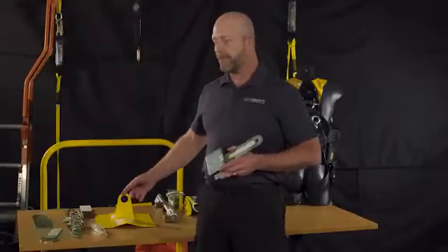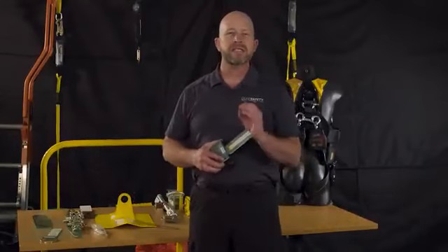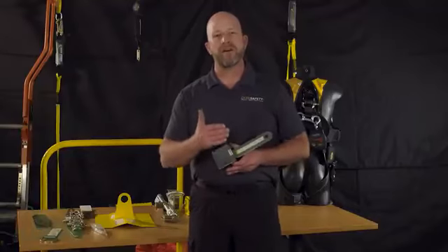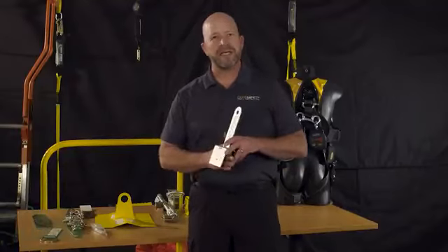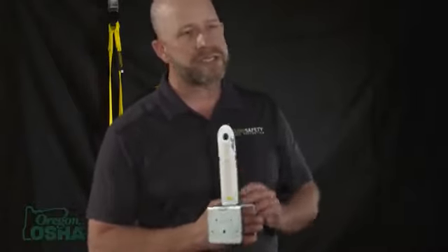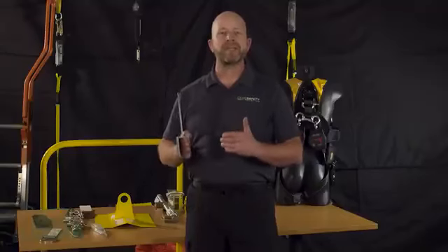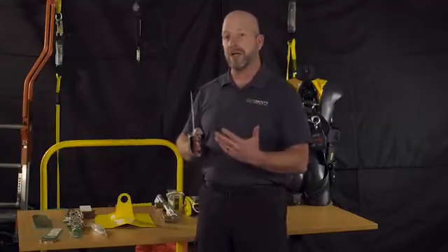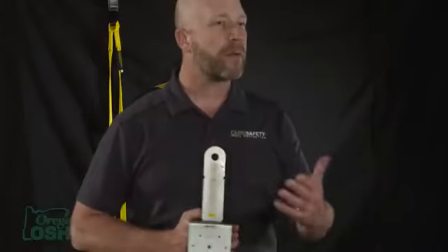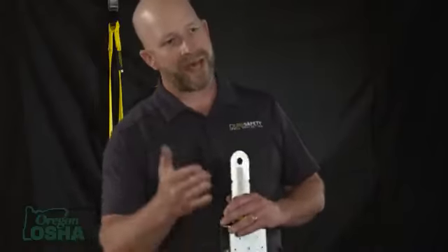Any anchorage attachment, beam strap, or other device, it is still imperative that when we're on site, other than following the manufacturer's instructions, that we still verify that the structure that we affix this to isn't just something random, that it is still evaluated either by a competent person or by a qualified person. Laying one truss doesn't make it structurally sound, and at some points, no doubt, you will have to have somebody actually do engineering or prove that it is capable of withstanding the forces. We talked about working on top of a top plate, and that the framing is up, but is it really an anchor?